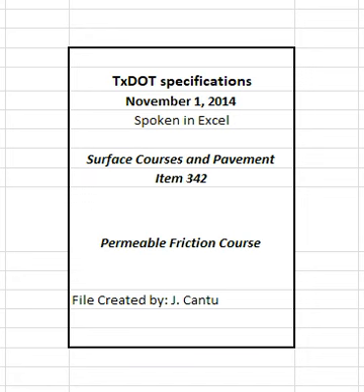2.3.2 Asphalt rubber, AR, binder. Provide AR binder that meets the Type I or Type II requirements of section 300.2.9, Asphalt Rubber Binders, when AR is specified unless otherwise shown on the plans. Use at least 15% by weight of crumb rubber modifier, CRM, that meets the grade B or grade C requirements of section 300.2.7, Crumb Rubber Modifier, unless otherwise shown on the plans.